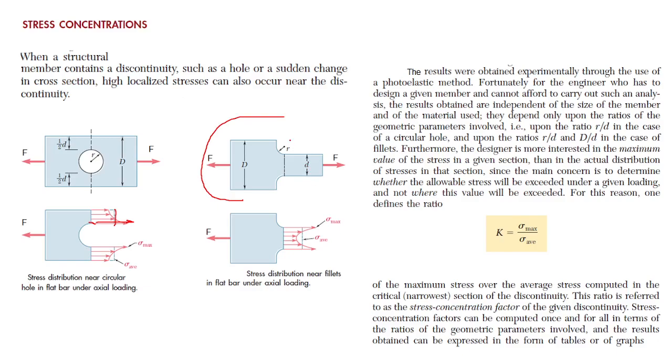The engineering solution to decrease the maximum stress is to avoid using sharp edges and sharp corners. We round the edges. Interior edges are to be rounded to prevent weakness and to decrease the stress concentration.